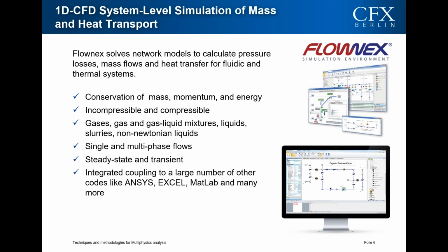And for that, you can use a software which is called Flownex. Flownex is a CFD solver which solves network models to calculate pressure losses, mass flows, and heat transfer for fluidic and thermal systems. The big advantage of Flownex, it's a 1D software, but it's a CFD solver. So it means it solves for the conservation of mass, momentum, and energy. You can use incompressible and compressible medium. You can have some gases, you can have some liquids, you can have some mixture of gases and liquids,